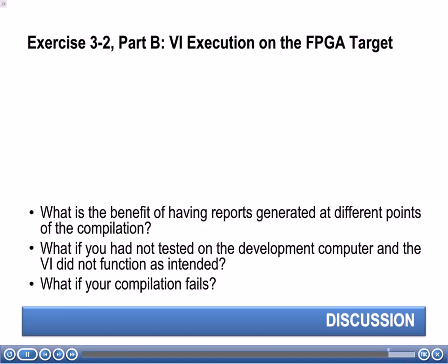Let's look at the next one. What if you had not tested on the development computer and the VI did not function as intended? This is something you definitely want to think about before you start developing. If I create an FPGA VI and don't check whether the behavior is correct, and I just compile it, maybe it takes an hour to compile. After an hour, when it finishes compiling and I run it, I see that I made a mistake in my programming and didn't have the right logic. I basically wasted that entire hour of compiling when I could have caught that much earlier.